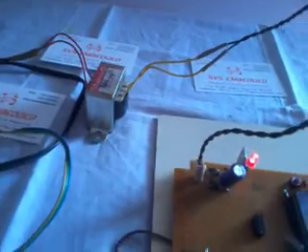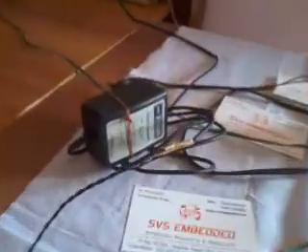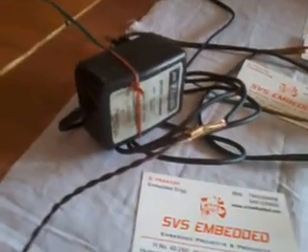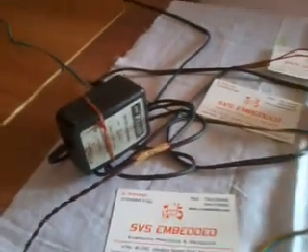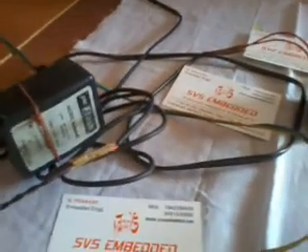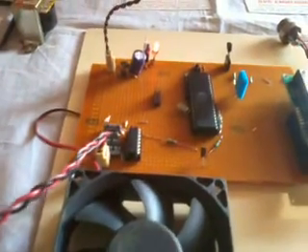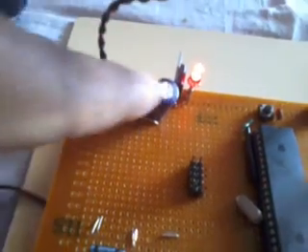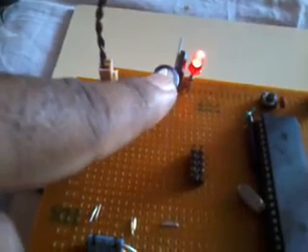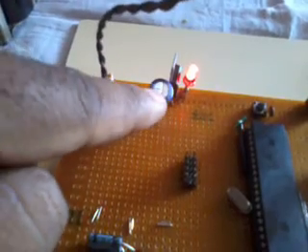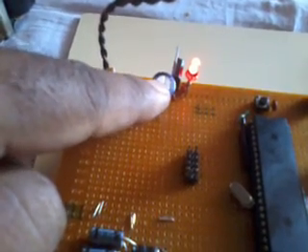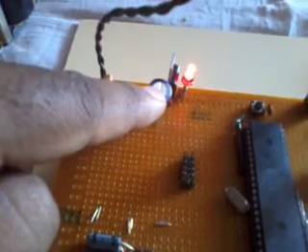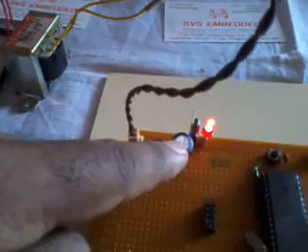First of all, I used a transformer. You can use an adapter also. It's a 12-volt adapter, most probably available in your country, with 750 milliamp or 500 milliamp current. These all utilize only a 5-volt power supply. That's why we are using a bridge rectifier and one filter capacitor, a 1000 microfarad, 25 volt electrolytic capacitor. The main purpose of this capacitor is to eliminate the ripples of the AC transformer.